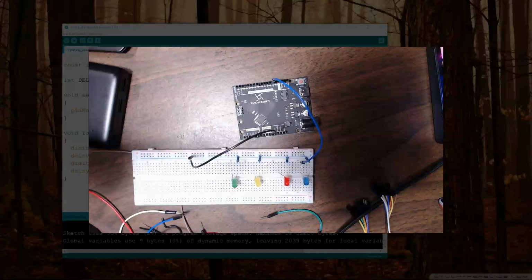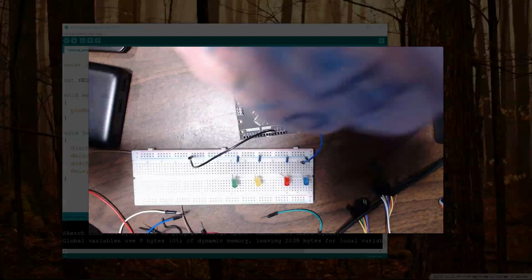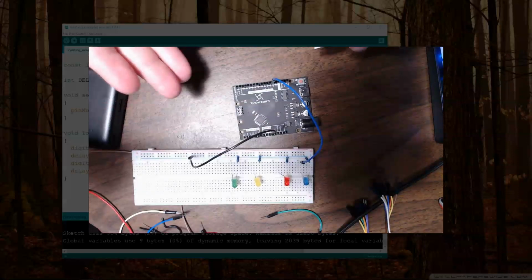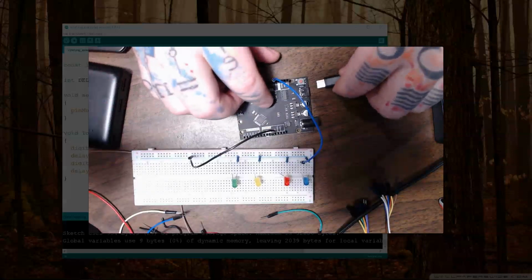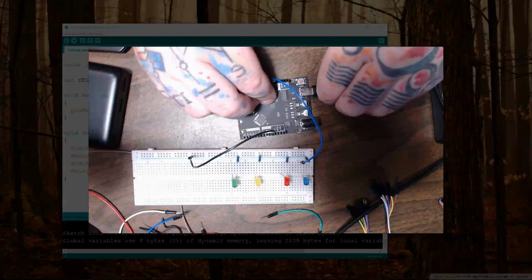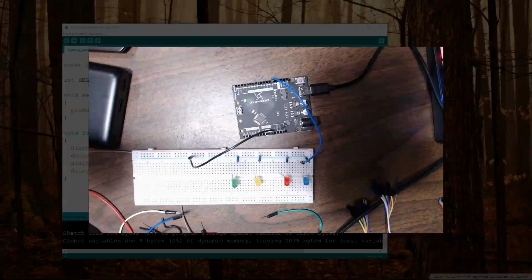So if we're ready to do this now, this is where we go back, and if we bring up the circuit board, we want to connect this now. The USB cable that's plugged into the computer, we want to plug in our Arduino. So I've got the wiring done. There's no power. I'm ready just to upload the actual code. So boom. Plug in my USB cable, which will connect it to the computer itself. So you can see the button. It's just running right now. There's no code on it. It's running whatever program was stored onto the controller chip here before.